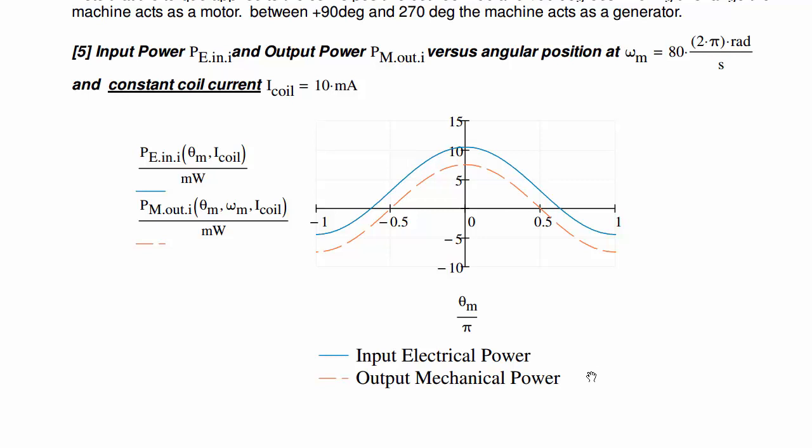In this case, the only place that we can lose power is in our resistor. Recall that we're not modeling the frictional losses or anything. Any mechanical output power, the orange here, will ultimately go to feed the rotational losses, static or Coulomb or viscous.